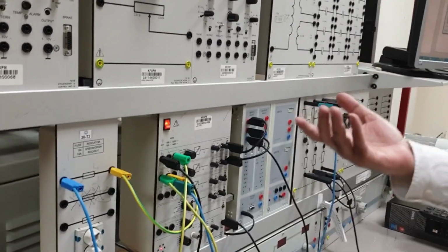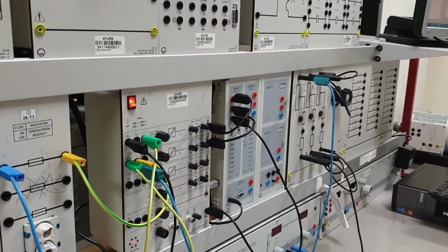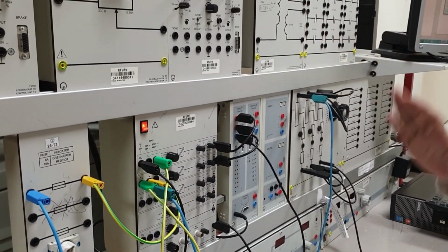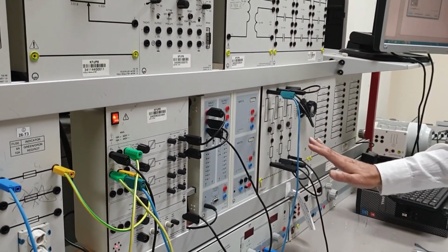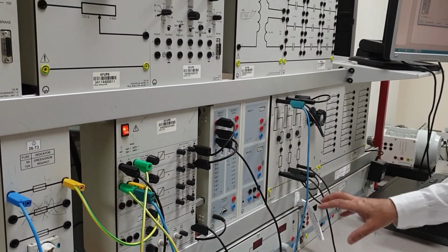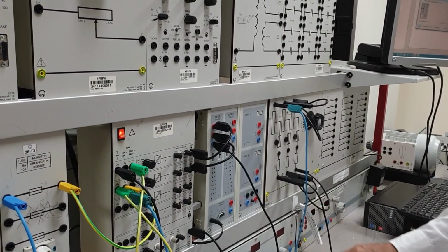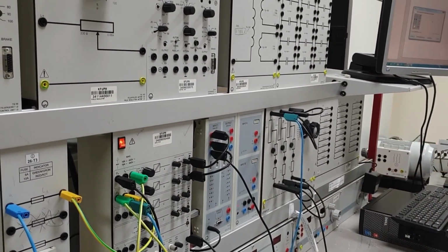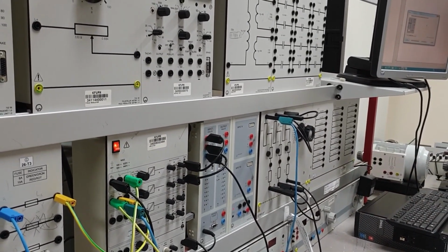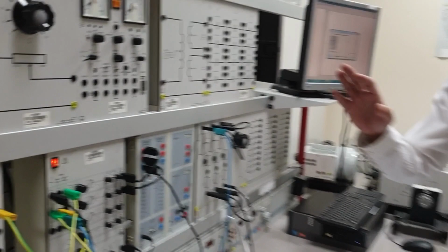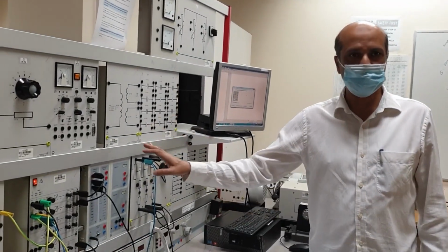Okay, so that's the function of the fuse. We always connect our equipment through the fuse. So from the power supply, we always take it to the fuse, though it is not shown in the circuit diagram. For DC, only the positive will go to the fuse, the negative you can directly connect. And for AC, the neutral is not to be connected to the fuse, but if you are using three phase, all the three phases L1, L2, L3 will be connected to the rest of the circuit through the fuse.